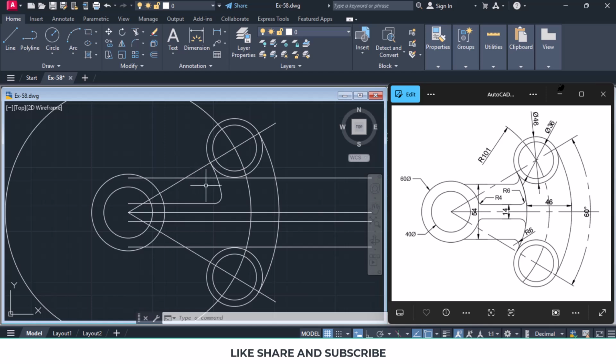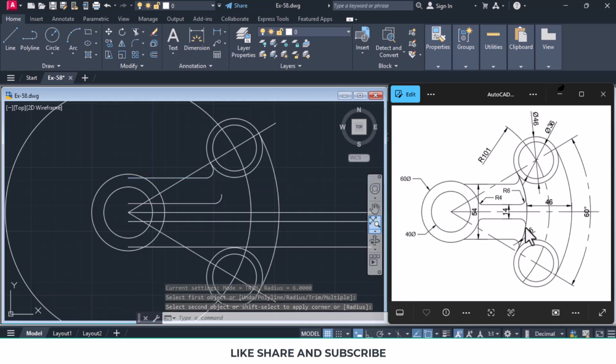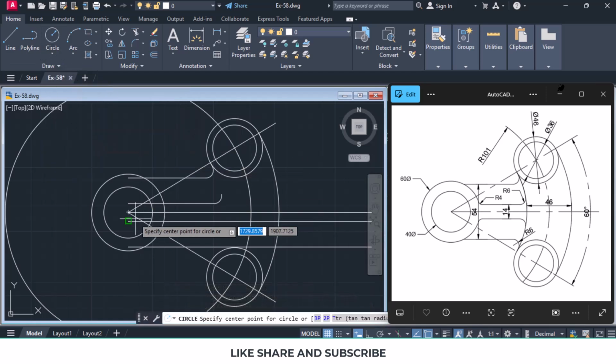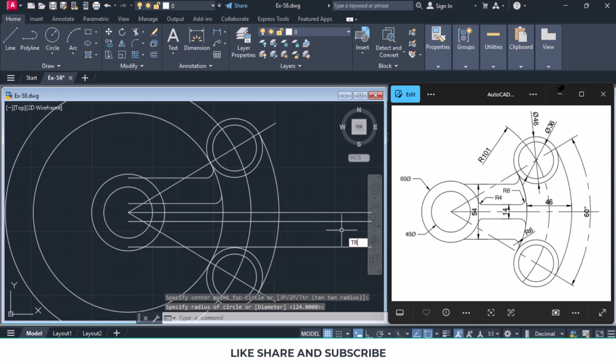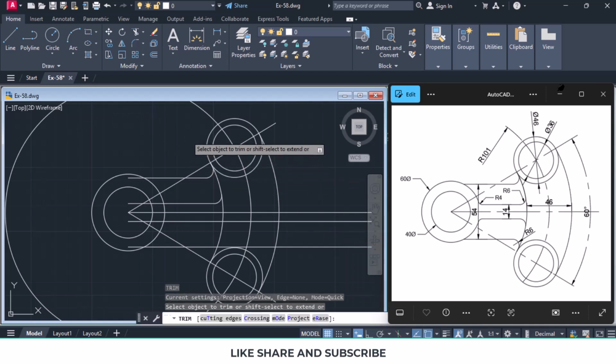And same way on the top also, we want this also to be filleted at a radius of 6 units. As you can see over here, it's written 6 units. So again we type F for fillet. It remembers the previous radius, so we click here and we click here. However, you can see this arc is gone. So we will select circle and we'll select center radius. This as a center point and intersection of this, and TR for trim, and trim the unwanted part. So our arc is back again.